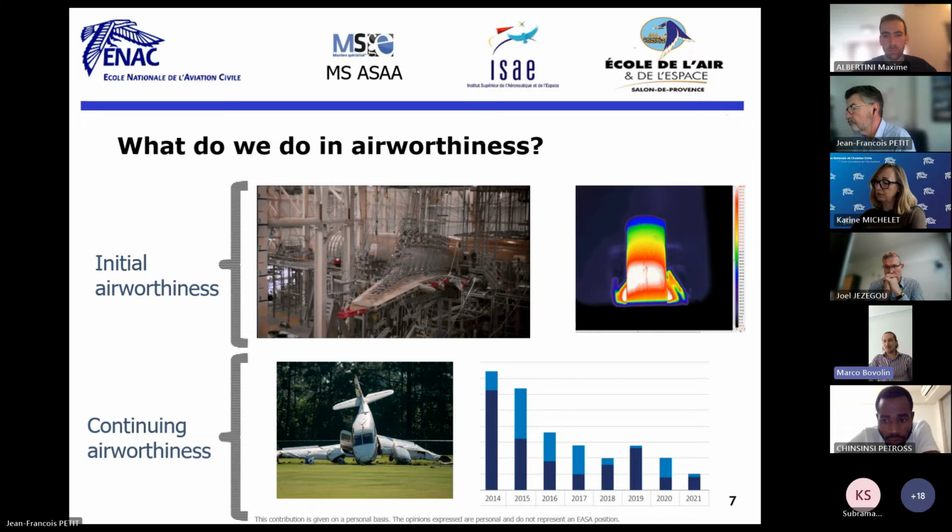And again, there are interesting design cases. I thought of this historical one from the 1940s. We had lots of B-17 bombers that were crashing at takeoff and landing. So they increased the training of the pilots, but still the pilots were making a mistake. They were confusing the landing gear lever with the flaps lever. So they just had to switch the knobs, and the moment they did that, the accidents disappeared. Well, almost disappeared. Just by analyzing what happened during the life of the aircraft, we could amend the design to achieve a higher level of safety.